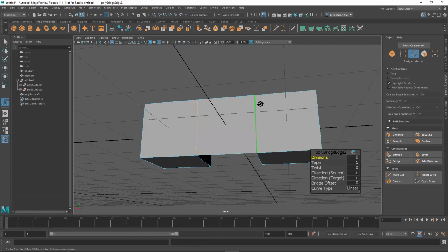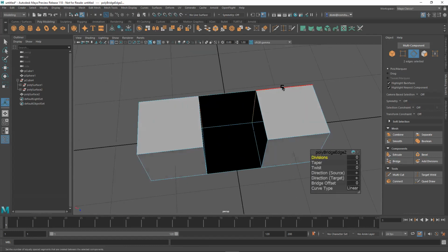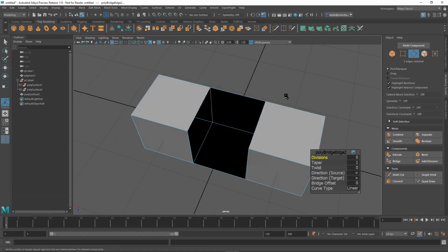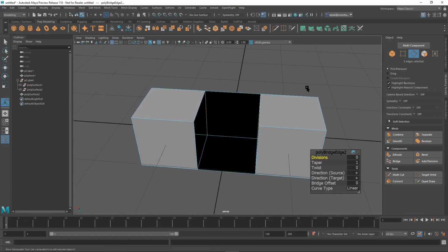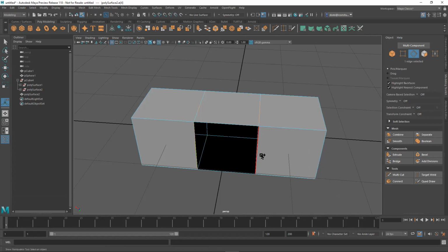There you go. Say you modeled 2 separate objects, more complex than this cube, but with similar face numbers, and you wanted to put them together. You would put them in positions next to each other, then go to combine, and then go to bridge. I can also type the G key for the last command. G just repeats the last command.